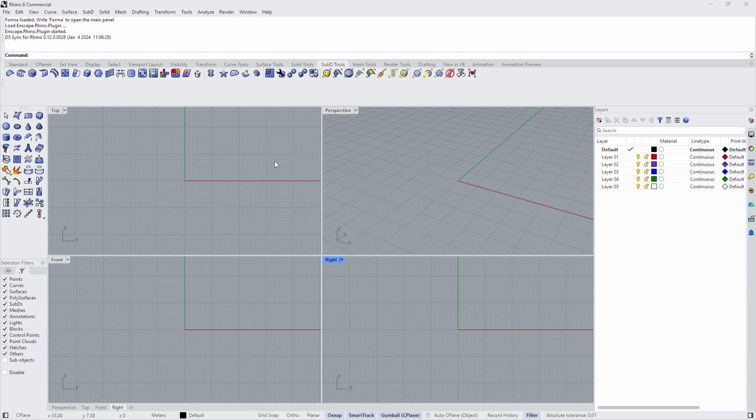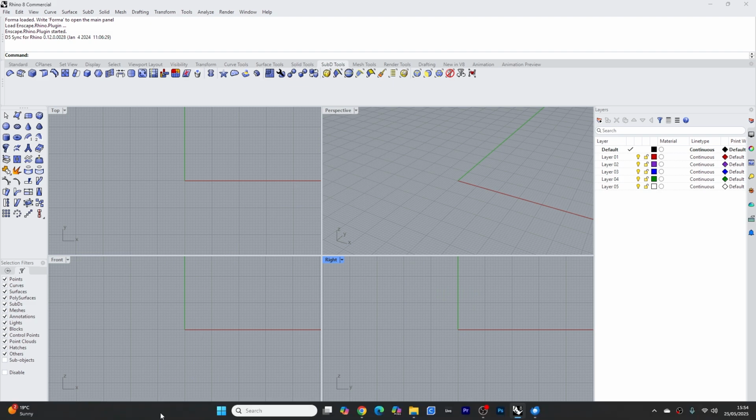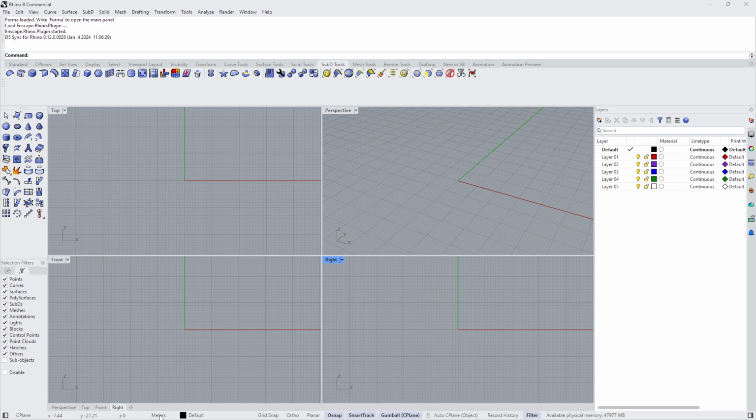All right, just one thing before we go into Grasshopper. This is another thing where a lot of people miss the point. The units are absolutely key in that software. So that means any wind analysis, most wind analysis measure wind in meter per second. And that's why your units should be meters. Your units should be meters. Any other units might cause issues. So don't run in millimeters. It will just create issues.